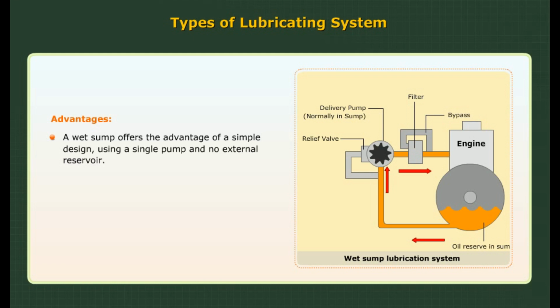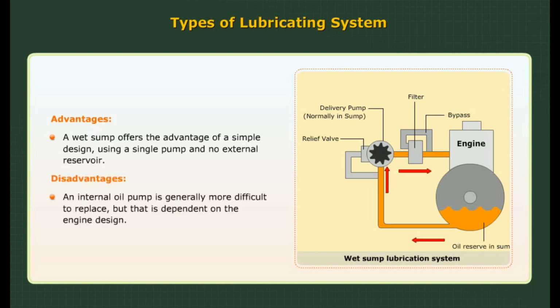Advantages. A wet sump offers the advantage of a simple design, using a single pump and no external reservoir. Disadvantages. An internal oil pump is generally more difficult to replace, but that is dependent on the engine design.